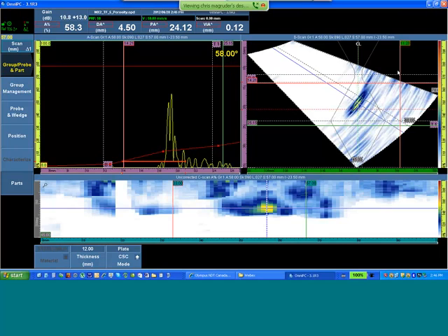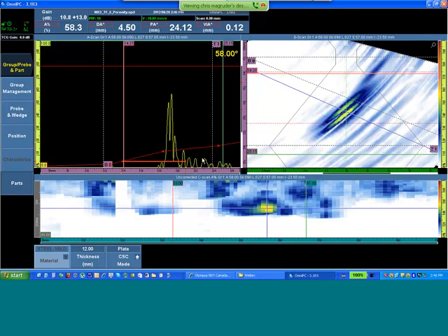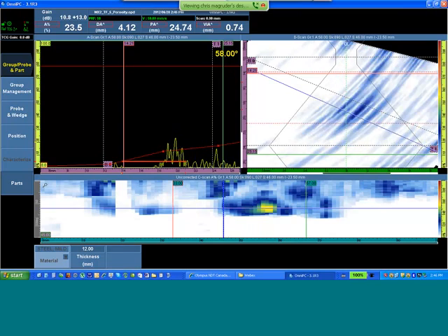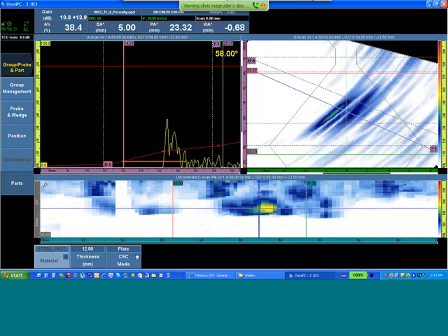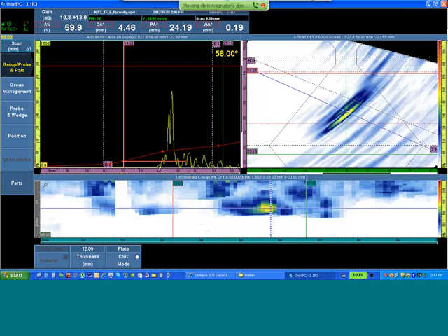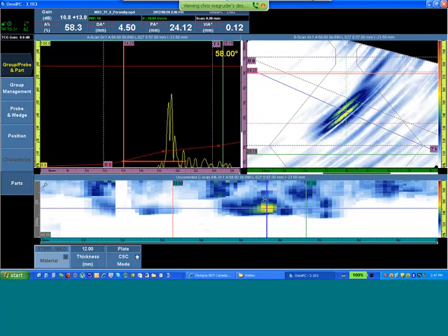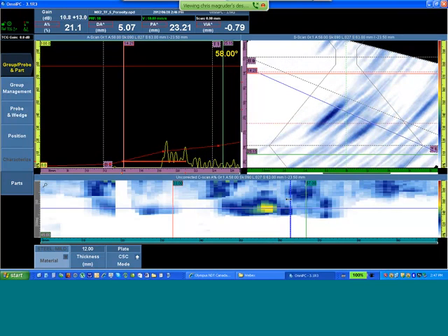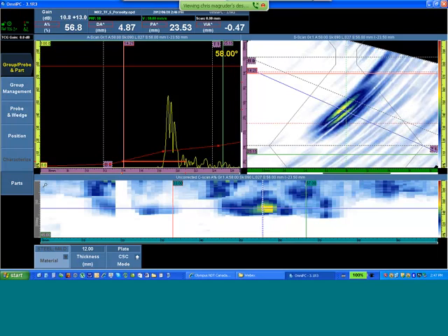was it detectable from both sides of the weld when that's possible as a criteria 2, and the third criteria is the A-scan characterization, also the S-scan characterization, what it looks like. So here we see a volumetric flaw, multiple peaks, multiple facets, a very long rise and fall echo dynamic, and obviously it looks like porosity, and that's what it is. Sometimes this is difficult to distinguish from slag.